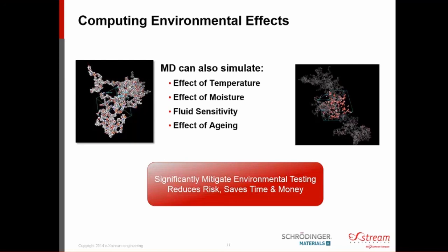And so what you can do is get the pristine polymer properties, look at how different ratios of the epoxy and the amine might affect your properties. And then you can start to also look at what might happen to your system as different things happen, like you get moisture ingress into your system. And this allows you to very quickly screen through different polymer systems, as well as understand how the polymer affects your properties overall, and what might be affecting your polymer properties.